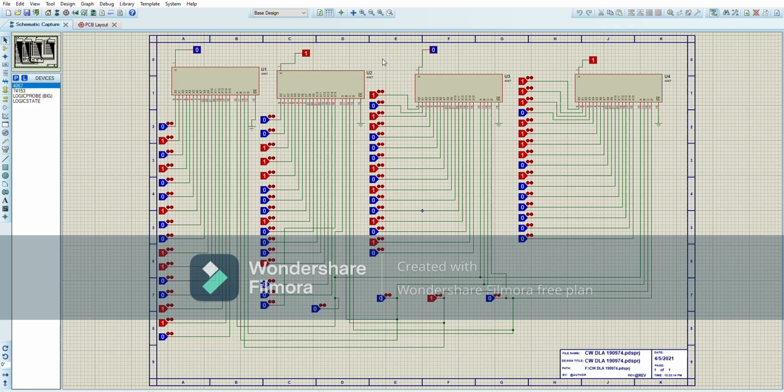The basic difference is that a mux has only one output, whereas a decoder has multiple outputs. In this, I've used 4x1 muxes with 4 inputs, that is A, B, C, D, and 1 output.